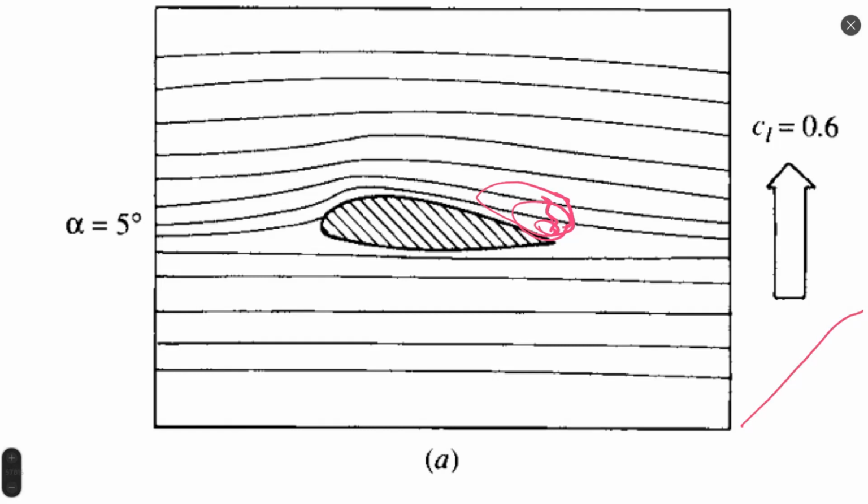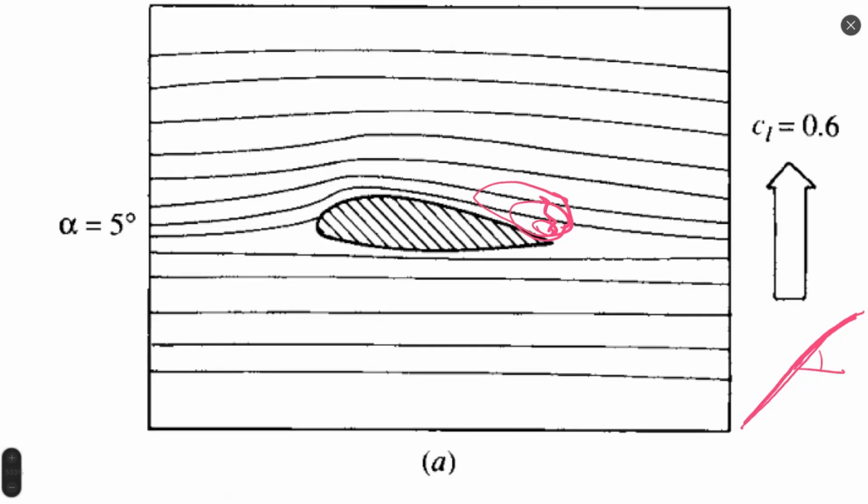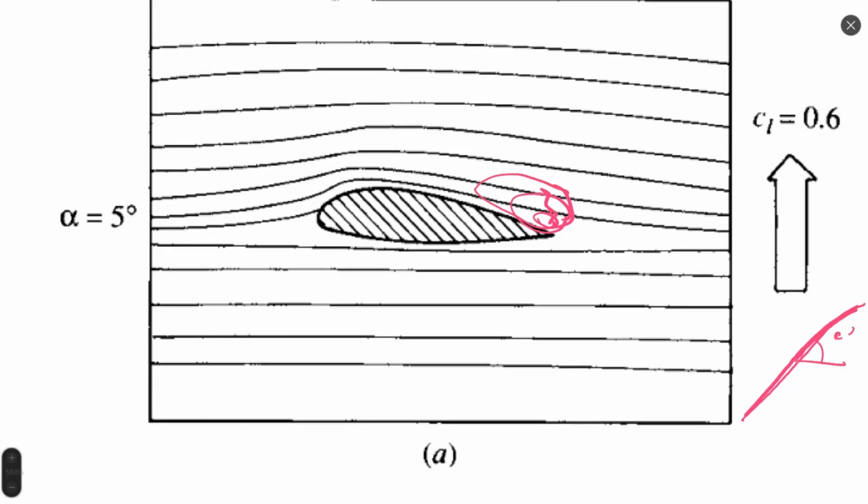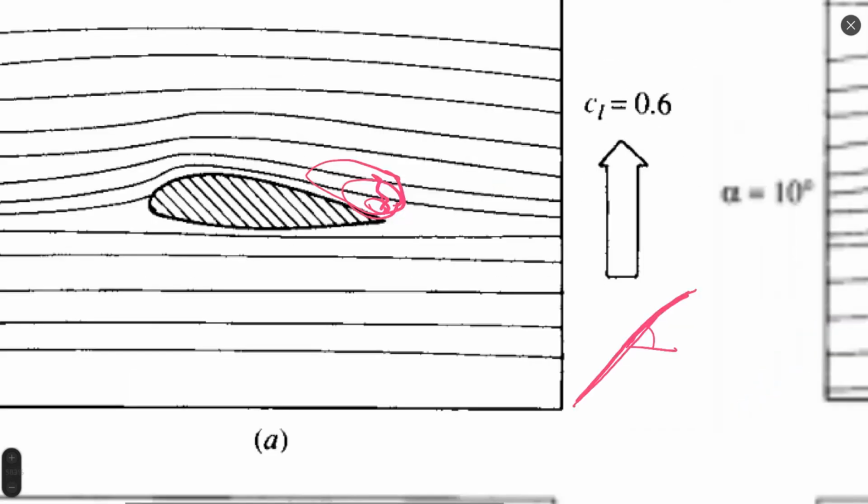So we cannot say that only when flow separation appears, flow starts to suffer and lift coefficient starts to drop. No, I think lift coefficient starts to become nonlinear. So there is a curvature in lift coefficient somewhere where we observe the presence of flow separation. But it will not start to decrease. I think the slope of lift, or inclination of this curve, which is called lift slope, how we can define it is CL. Oh, let's see. That's right here.